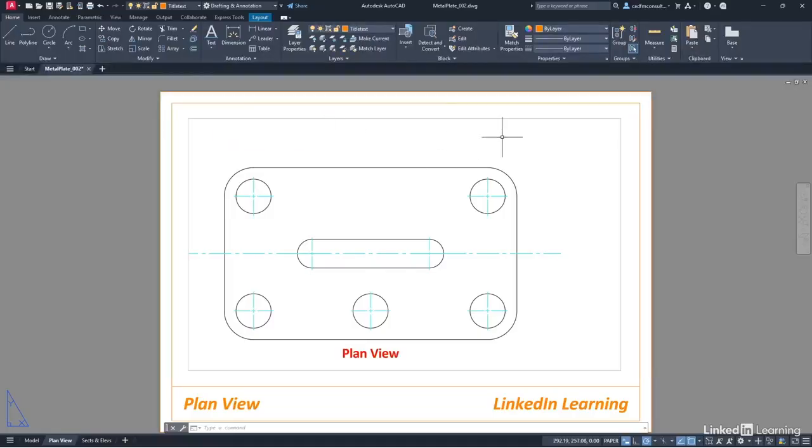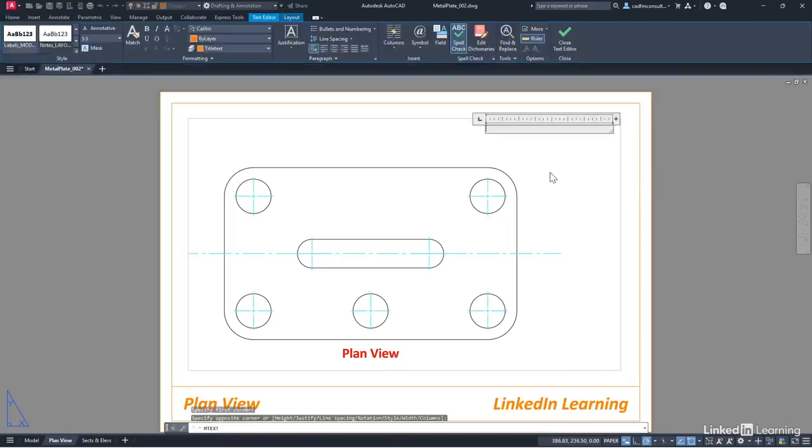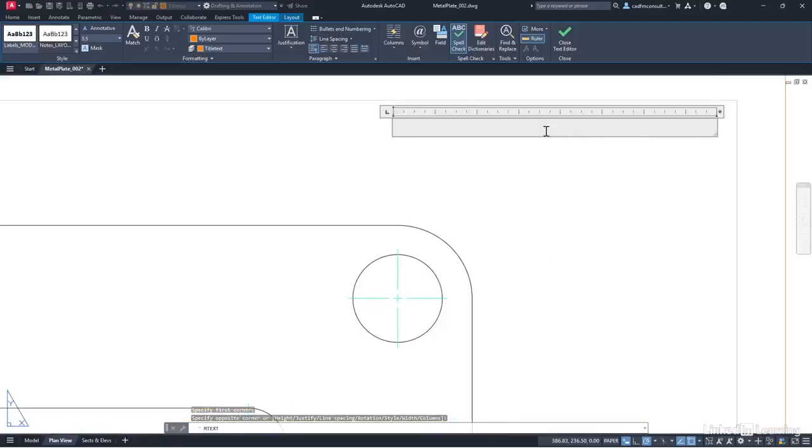We're now going to place some multi-line text. So we go to the annotation panel again, click here on the flyout like we did previously, but multi-line text this time. Click and drag like so to form a little rectangle shape. Multi-line text goes into an area rather than just lines of text. So pick a spot about there. And we're just going to type in some text. You can zoom in if you want to.